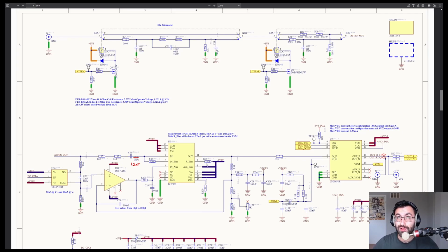And I think I'm just going to go with the datasheet approved bias value. It's not 30K. I tested with 30. It's actually like 35.7. But I think I'm just going to do that just because that way I can use a lot more of the datasheet specs versus the few graphs that actually mention running it in 100K. And then we can eat the current difference, because with the custom FPGA module, it's going to use a lot less current as a whole than using the Trenz Electronic modules that we were using. So that's no longer as much of a concern.